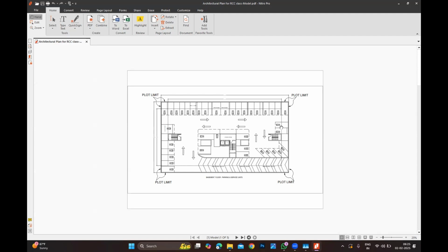The reason is, whenever you have a basement, it is complicated, not to the extent of the structural design, but you need to understand the complication in placing the columns. People tend to always come from down. Whichever floor starts from lower, they start the placement of columns from there, which is completely wrong.